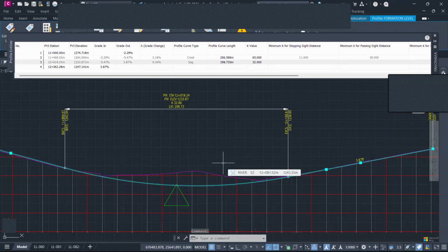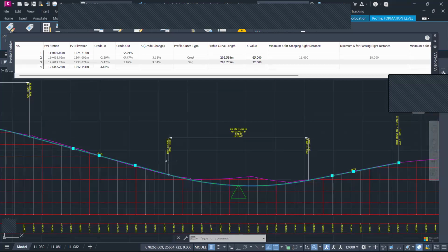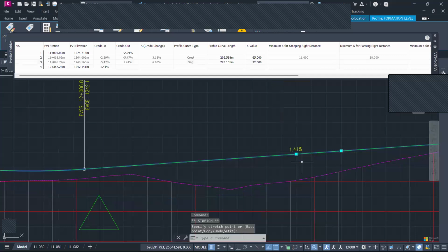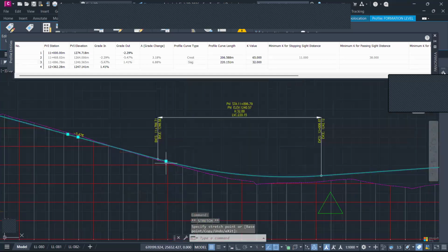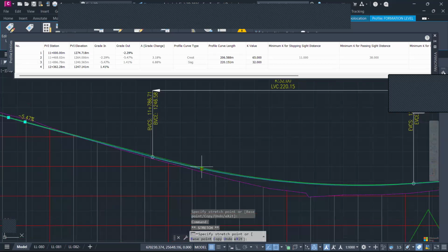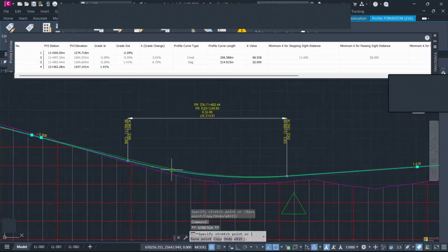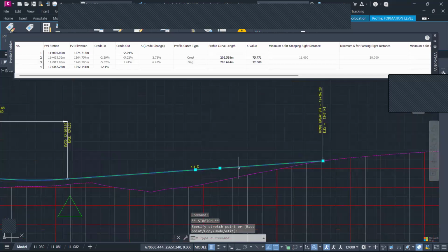We are cutting already in a cut section. So how do you modify this? You use node edit. You can use this node here to move your curve a little bit to the upper side. These are now manual edits. You can move this tangent in that direction.